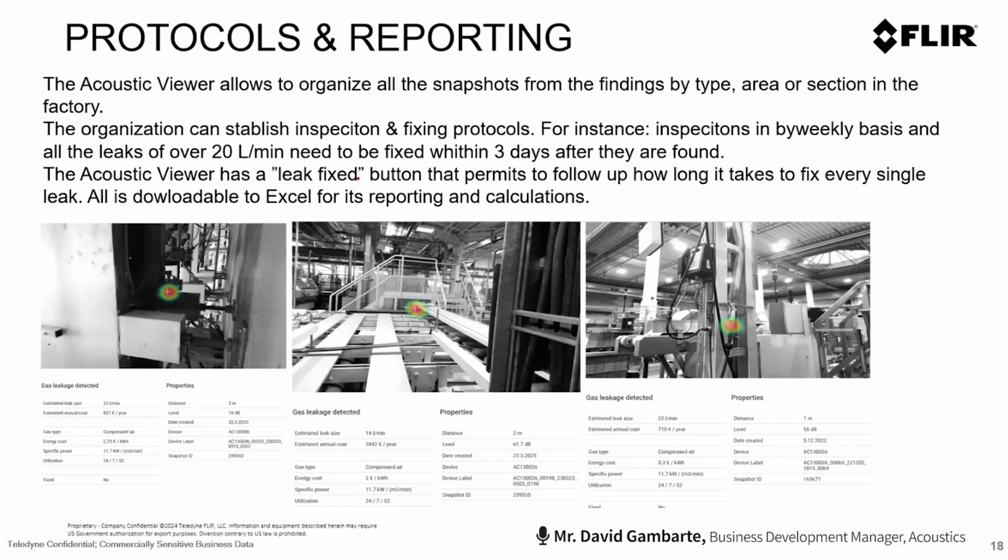Any leak that is over 20 liters per minute, or 30 or 40, depending on your priorities, or you say, no, all the leaks have to be fixed. And then you say, okay, we fix all the leaks within 2 or 3 days after they are found. So you can do this with our tool. You can set this protocol and you can follow this up. And we consider it a very powerful solution for you.